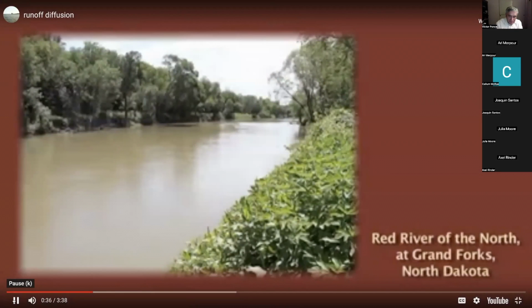Runoff diffusion is the spreading of stream flows longitudinally and or transversely, which leads to a reduction in peak flows. Runoff diffusion is responsible for the size and magnitude of flood discharges. What causes runoff diffusion? There are natural and artificial causes. In large watersheds or river basins, the flow spends most of the time in the river channels. In river channels, diffusion can be longitudinal and or transversal.